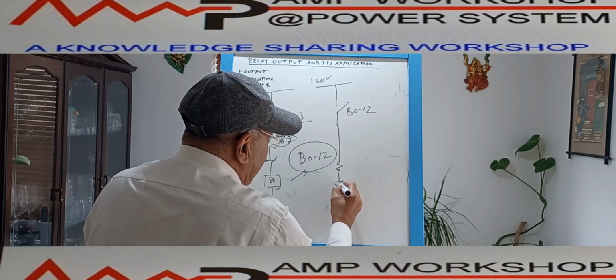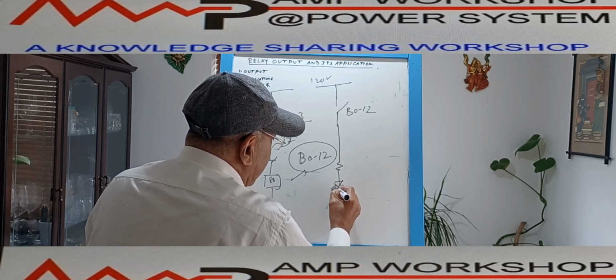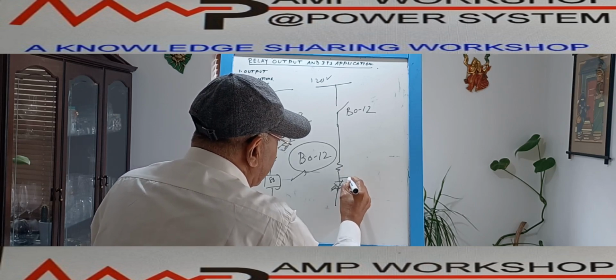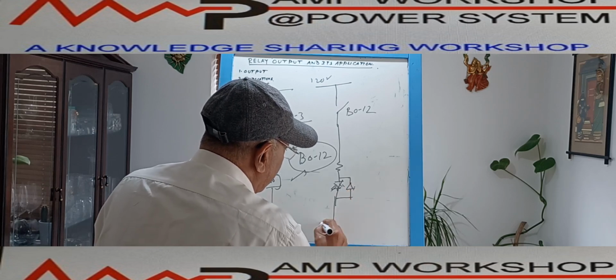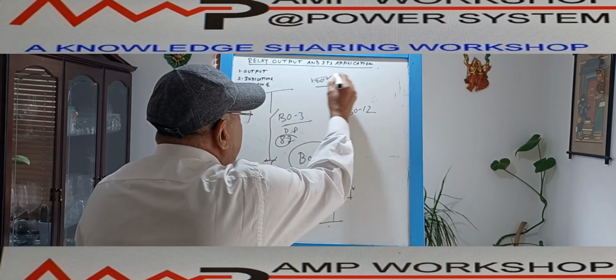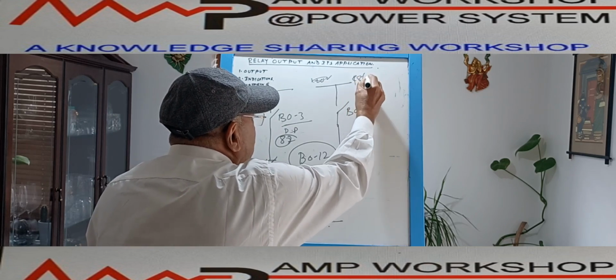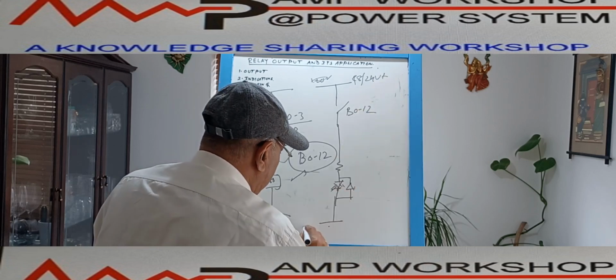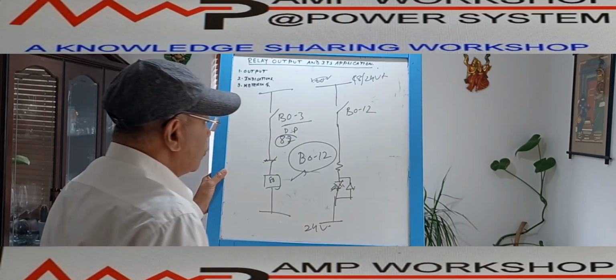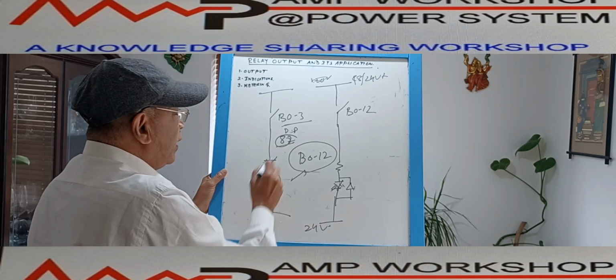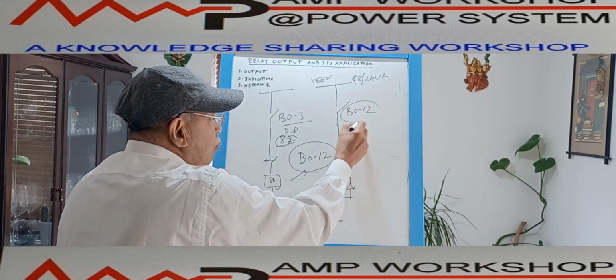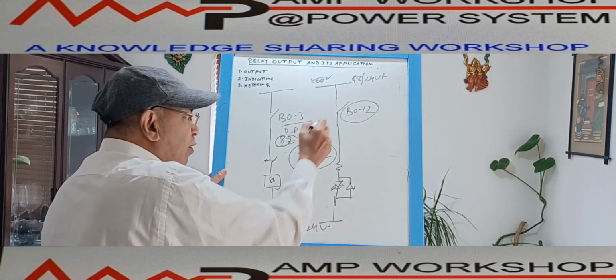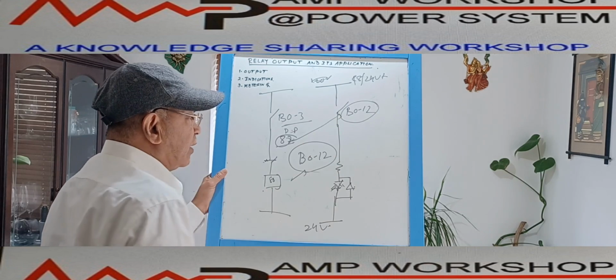We have seen the annunciator circuit, these are the LEDs, and then this is a reverse blocking diode, another diode is here, reverse blocking, and it is going to the 48 volt negative. Suppose this is 48 volt or 24 volt positive, and this is 24 volt negative. So the moment differential protection operates, it will not only trip the breaker through lockout, at the same time output contact 12 is configured for this protection. It is linked with the protection function 87.